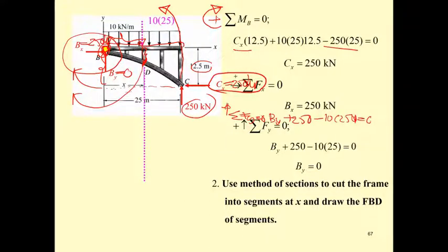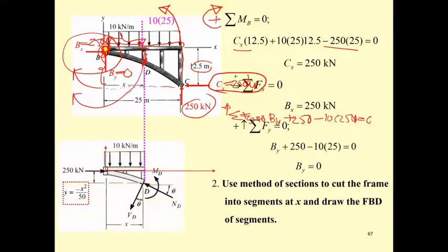So cut it here, project this into here, and then we have this as the y, and the same as this. And as the cut, since the arch is a kind of frame, a cut of the arch is going to produce the moment, axial force, and shear force.